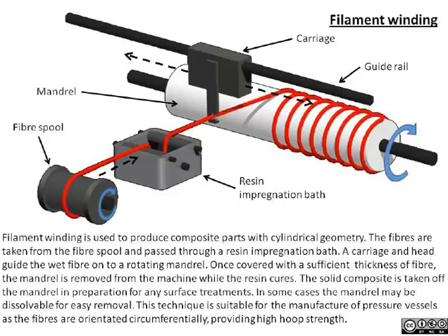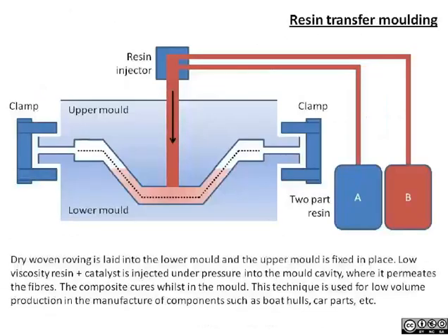Because we can achieve most of the fiber orientation in the hoop direction, these are obviously very valuable for pressure vessels. So you'll see pressure tanks made of these filament wound arrangements, and of course they'll have to bend around in 3D around the ends so that we can quite often have it continuous in sort of an ovalized 3D shape.